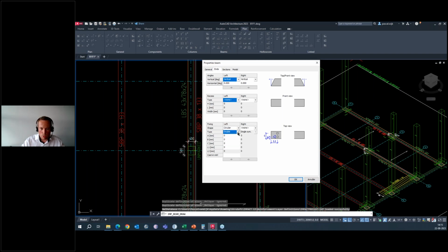So I can set a double one, a single, symmetric, but in this case I'm just using single, because then I have the freedom to choose what the distance is from the front side to the center of my hole. So yeah, let's take 45 and 230 because I know that, and 18. I can also add a custom material if you want to do that, and bam, there I got this one.